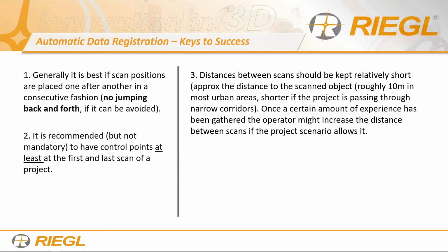Of course, the higher you get the scanner, the better angle of incidence that you'll have on horizontal surfaces. Vertical surfaces will get the range and the accuracy and precision of the point regardless of the range. But on ground shots, if you're on a tripod, you're limited, right? Your diameter of good returns is limited because of the shallow returns.